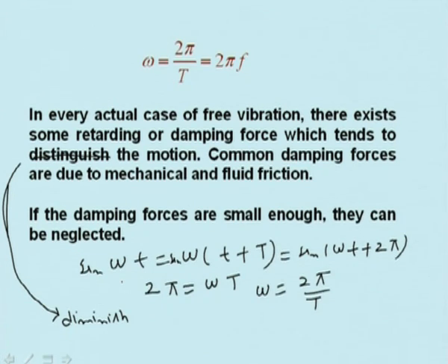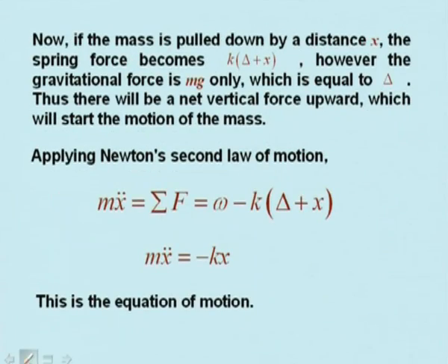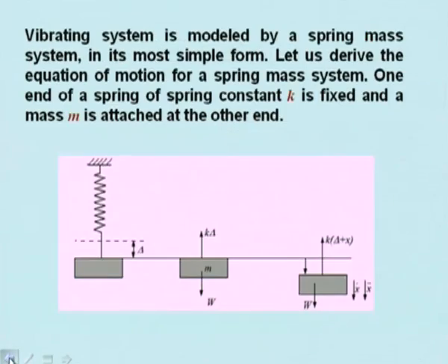Therefore, if the damping forces are small enough, they can be neglected, because they are very small. We can study for a considerable period of time the motion that keeps taking place, and the damping can be neglected. Moreover, from the designer's point of view, it is conservative to first study the motion without damping, and after that we see what the effect of damping is. Damping will have the effect of reducing the vibration.